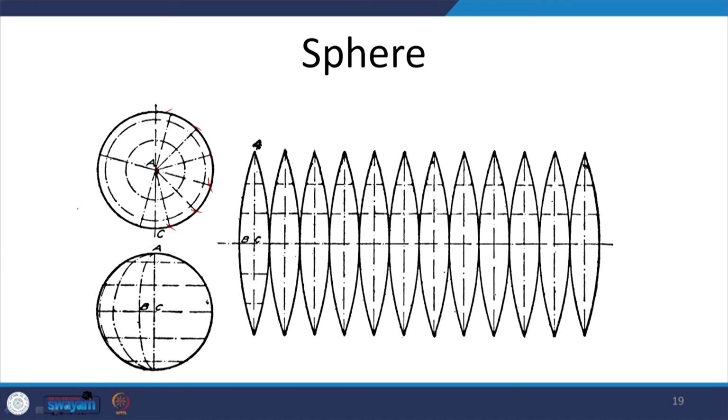So when we roll it over, when we open it, what we have is the diameter of the sphere. This line is equal to the diameter of the sphere, and at each end, what we are actually going to get is a single point. All these points are going to converge at this single point, and if we draw perpendiculars at each regular interval, so if the sphere is divided into 12 parts, we will divide it such that the last two parts are the halves of each part.